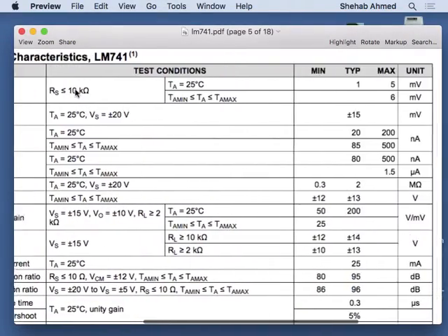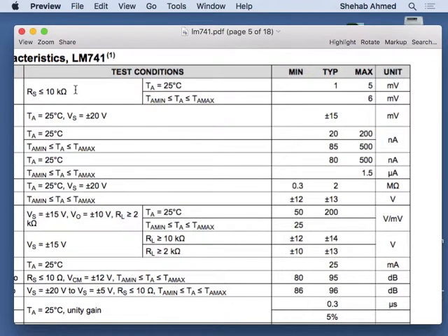So it's the input offset voltage. When you design this device, you get this offset voltage. Also, when you design this device, you will get a large gain. When you design it in a certain way, you will get a gain that is large but not infinite. Infinite doesn't make sense. Also, we said infinite bandwidth. Remember, that's one of the things we said about the op-amp. If I put any signal with any frequency, it will respond with a gain, no problem. But this is not true either.